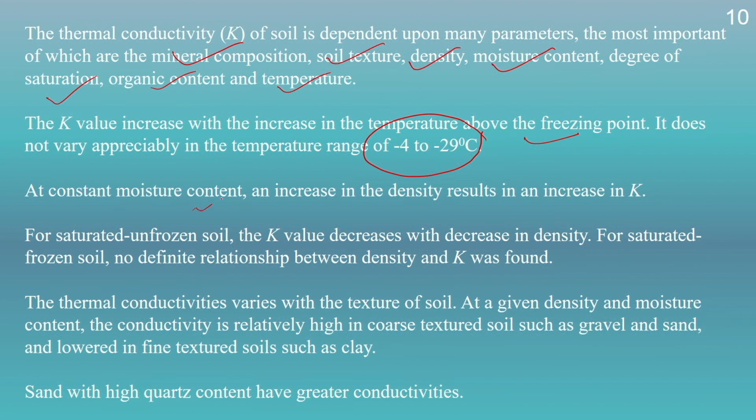Similarly, at a constant moisture content, an increase in the density will result in an increase in the thermal conductivity value. Similarly, for a saturated unfrozen soil, the thermal conductivity value decreases with decrease in the density, and for a saturated frozen soil, no definite relationship between the density and K was observed.